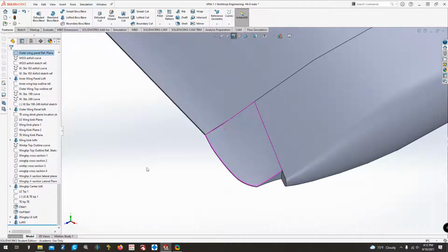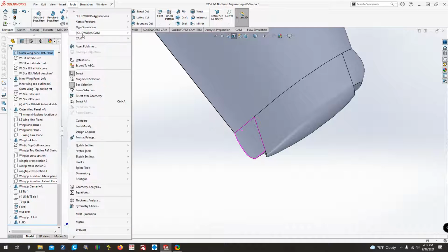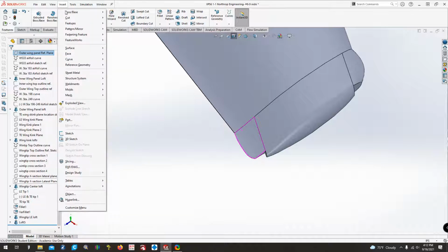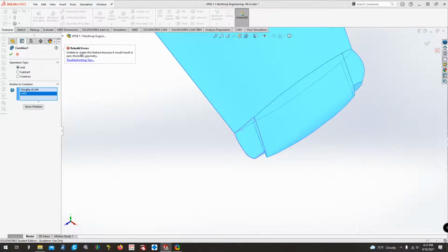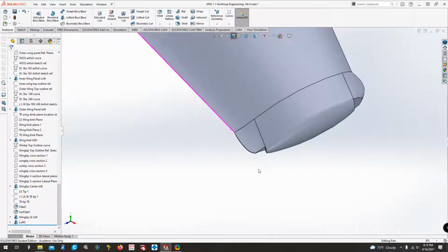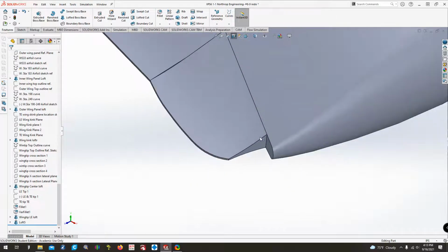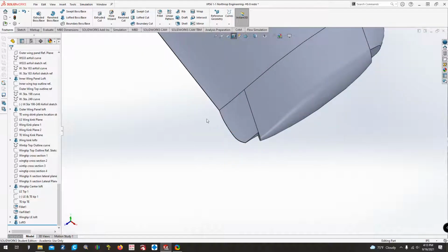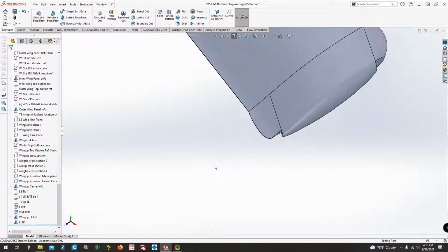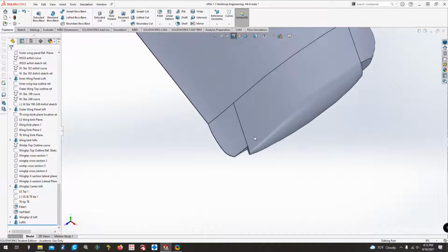off. We'll hide the curvature outline. And then tools. We'll come in and insert features and then combine. We'll combine those two and we'll make sure it's add. Then we'll try that. Now it won't let us do it either. So most likely there's just a minuscule little bit of a gap between these parts that I'll have to find the adjustment and the sketches to make it work.